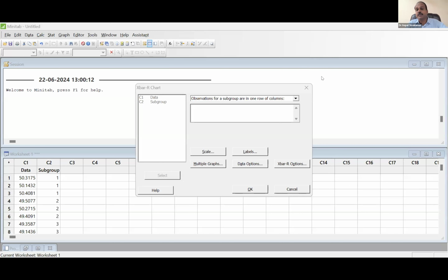One more thing, please note. If you look at the control chart, we only talk about control limits and the points. Am I right? But if you talk about CP, your USL and LSL also come into the picture. So even though your process is stable, your CPK can still be in trouble.